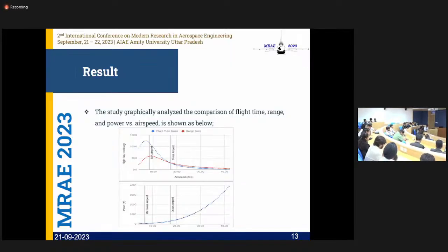Now, after we have done the mission profile and integrated the sensors, we are going for 4 basic ones: a GPS system, gyroscope, barometric, and infrared sensors. For the GPS system, we have used the u-blox NEO. The gyroscope will be the MPU 6050, and the barometric will be the BMP 280.